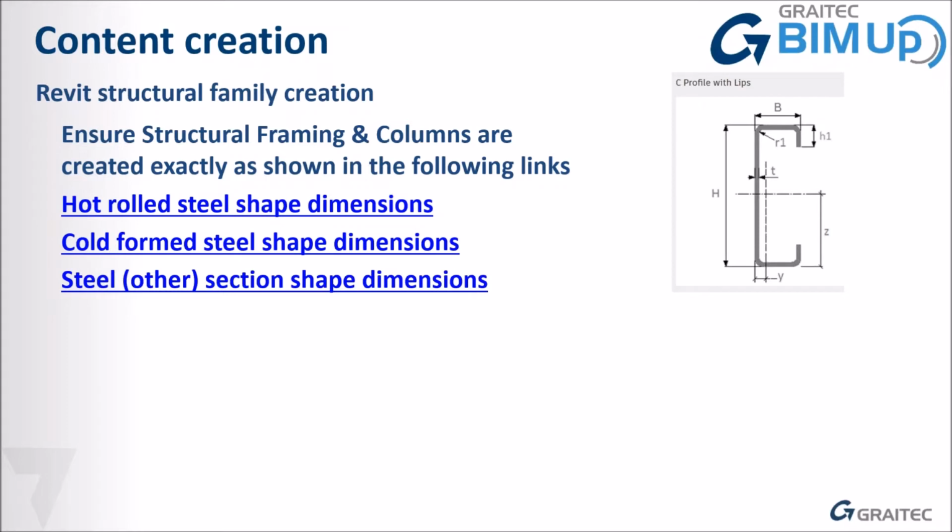What we would say is create one family, draw it as a 2-meter beam, and try exporting it to Advanced Steel. Then in another model, have a plain beam and a plain beam with a connection on, to make sure the connections work, because if you don't have it set up properly, the steel connections won't apply.